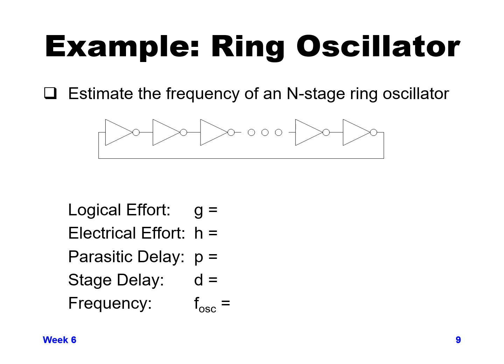We basically just have a series of inverters whose output leads back to the input. And if you construct it with an odd number of inverters, it will oscillate and cause a signal that will go from 0 to 1, and cause the next stage to go from 1 to 0, and then the next stage 0 to 1, and oscillate around the circuit. With an odd number of stages, it will continue oscillating around the circuit.